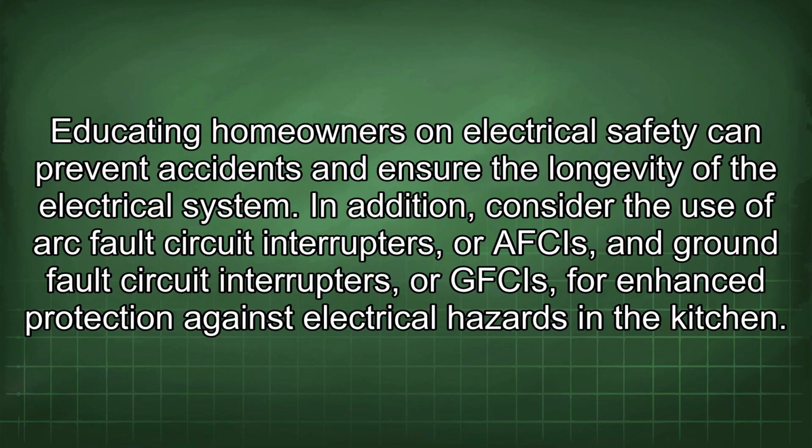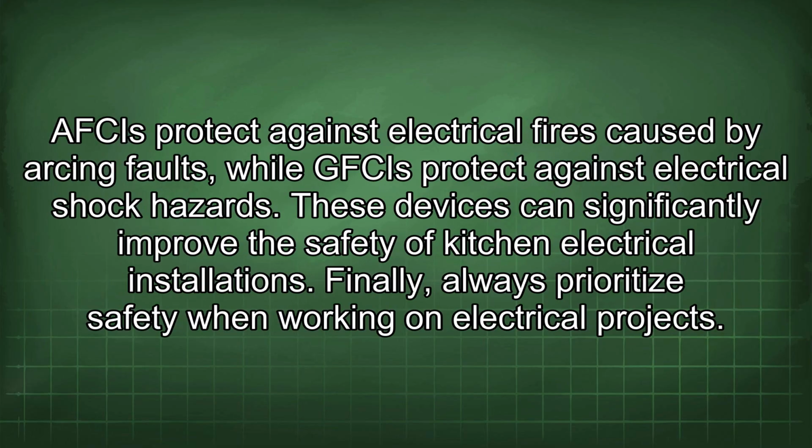In addition, consider the use of arc fault circuit interrupters, or AFCIs, and ground fault circuit interrupters, or GFCIs, for enhanced protection against electrical hazards in the kitchen. AFCIs protect against electrical fires caused by arcing faults, while GFCIs protect against electrical shock hazards. These devices can significantly improve the safety of kitchen electrical installations.